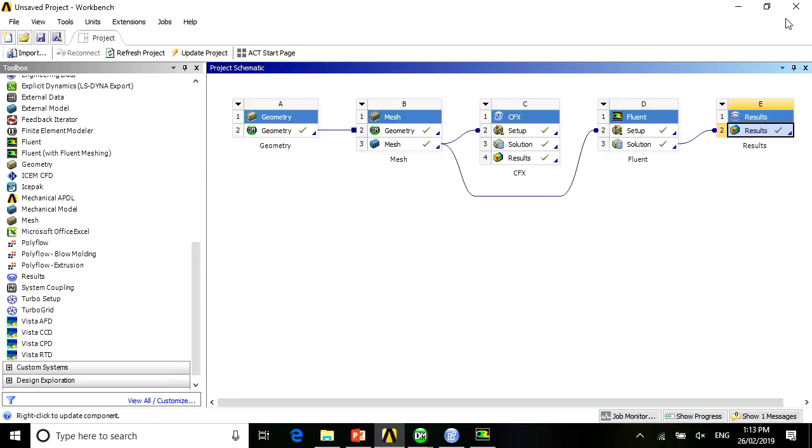They are not entirely different, but they do differ. There are 2 CFD programs that ANSYS acquired. CFX is called that because it started as CFX-4 3D. Let me say what is different. CFX does very well with multi-phase flow, like gas-liquid flows.